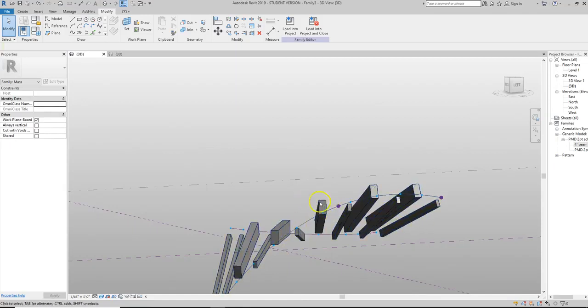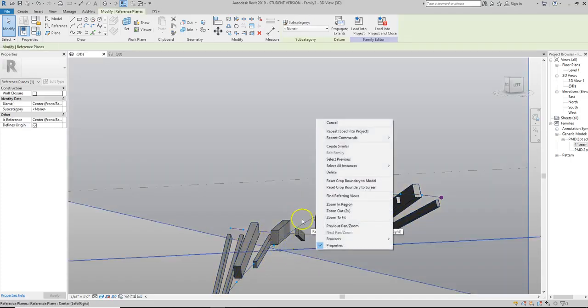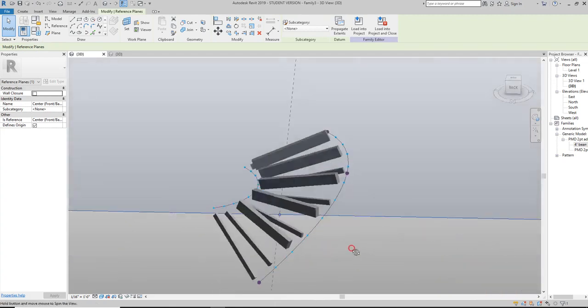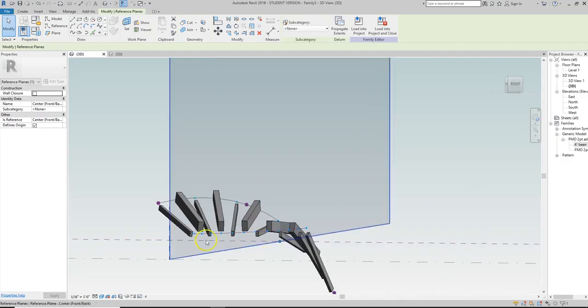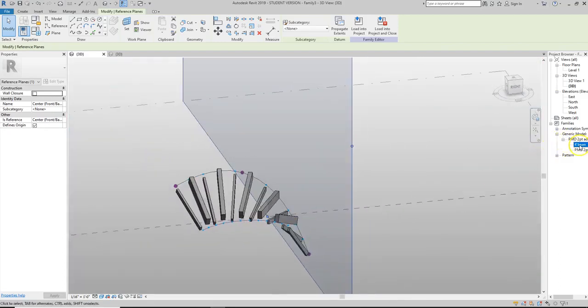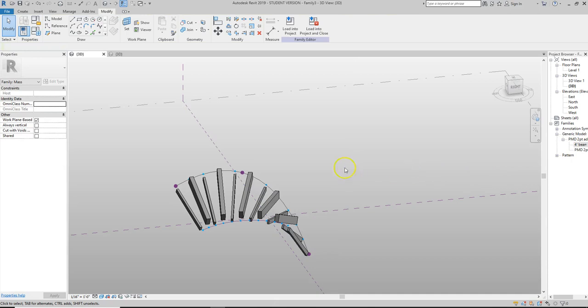Right now, these, when I put global, they're always going vertical, as we can see here. Sometimes we do want them to be along the edge, which then that would be host. This would be, let's say, structurally, they're always falling in plane. So this is how we'd want to create multiple beams and have different sizes. I would name each one and give different parameters, alter the parameters for them.